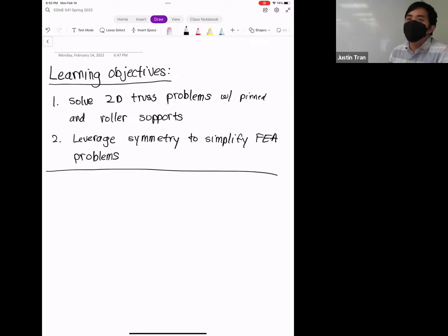You have a spring, and you have the two attached to each other, right? So F1, F2 is equal to K1, and then you have the big multiplier on the part where the truss is? Yeah, you just add them together. That's why I showed you, when things overlap, I draw the outline of where the stiffness is, and wherever they overlap, whatever's there from either stiffness matrix, you just add them together. I thought that was in the global system you showed us. Yeah, and in the global system, that's the only place where you combine them.